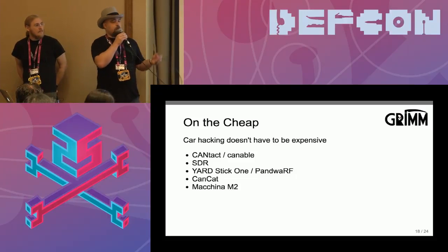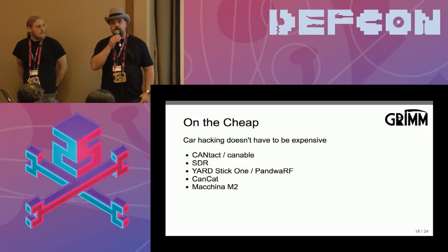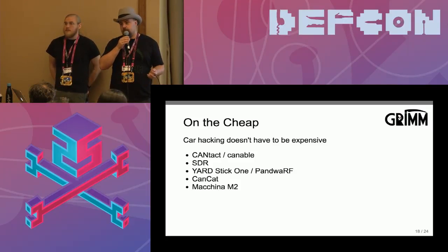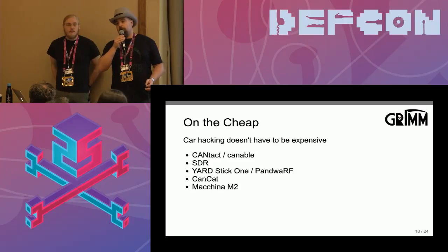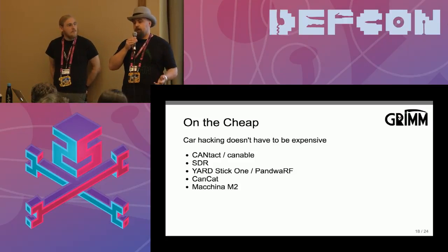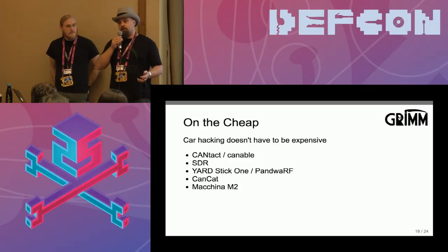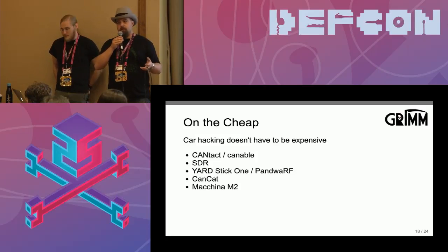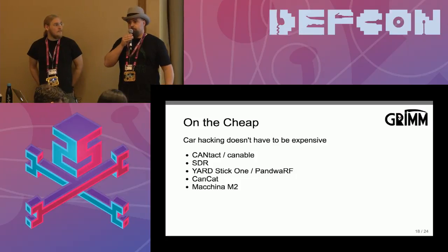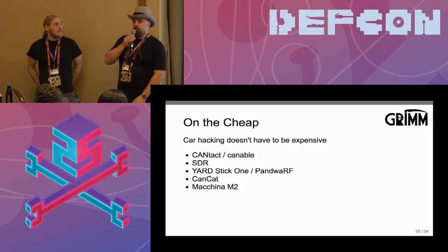CanCat supports what we call CAN in the middle mode, where you can isolate a device, basically use the 2 CAN transceivers as a pass-through, and you can also do filtering or modification of messages or block certain messages, whatever you want to do to screw with it. It's also really nice since CAN doesn't have a source IP address, or source address as part of the packet. If you don't know which device is sending a message, you can use that to isolate a specific device and then see which messages that device is actually sending. Otherwise, the CAN bus is just nothing but messages going back and forth and no idea where they're even originating from.